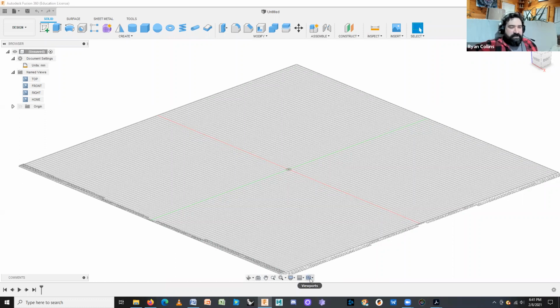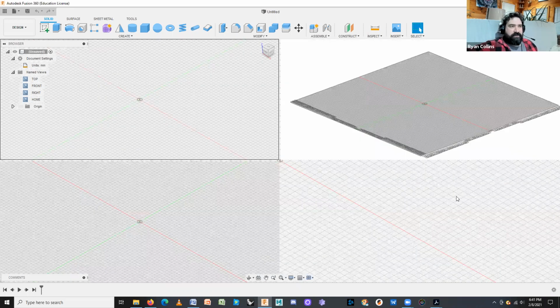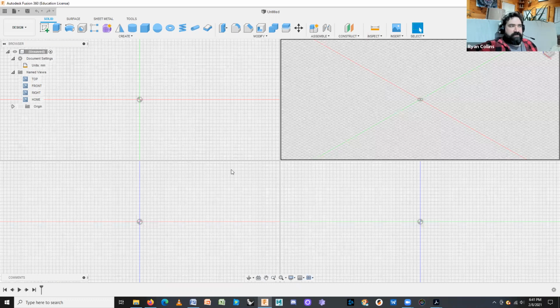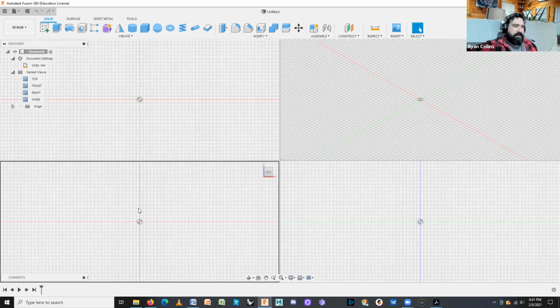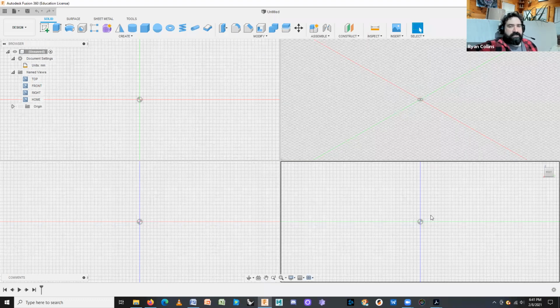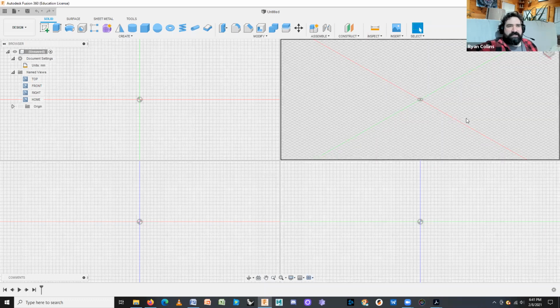In the bottom center tools, here at the bottom of the center of the screen, far right, viewports. If you click that, you have the option of multiple views, or as it says on here, you can press Shift exclamation point. That changes the default view settings to your 4 views. Top left is top, bottom left is front, bottom right is right, and your top right view is your perspective view.